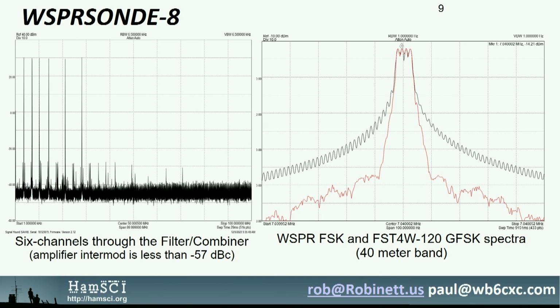And there's filtering going on there as the frequency, instead of jumping from one to the next, kind of gradually slides from one to the next. That reduces the modulation artifacts, and you can see that inner spectrum shows how much cleaner that is. This is low power, it's WSPR, everybody uses WSPR, and nobody really cares about the sidebands. But FST4W is cleaner, I like that, but that's because I'm a nerd. And well, that's about it.